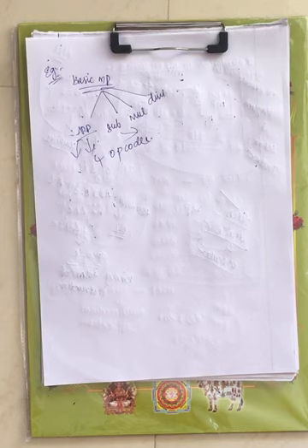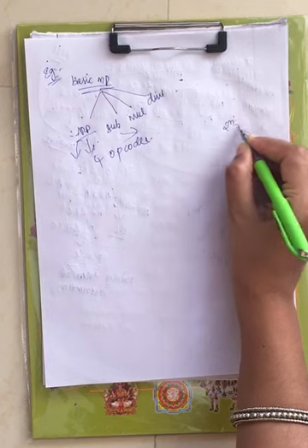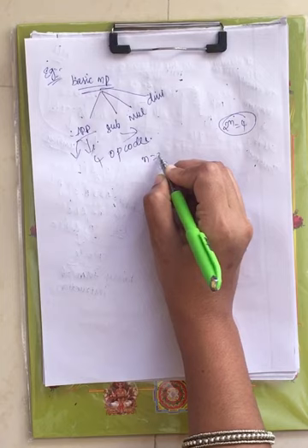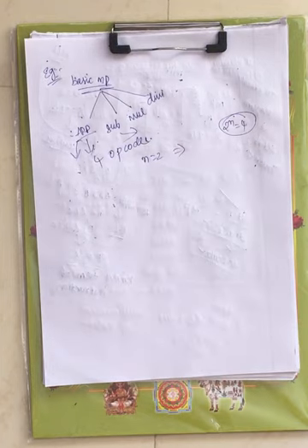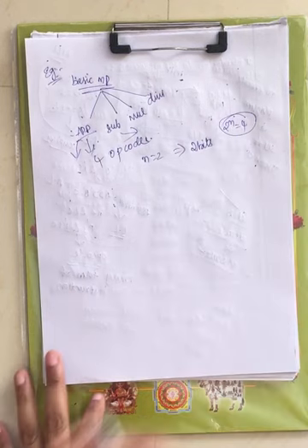Now consider the basic microprocessor with 4 instructions. Since it has 4 instructions, you will have 4 opcodes. Now opcodes will be of how many bits? 2 bits, since 2 power n equals 4. Remember this scenario, based on this you will get the number of bits for the opcode. What is the value of n? n equals 2. So opcodes will be of 2 bits.